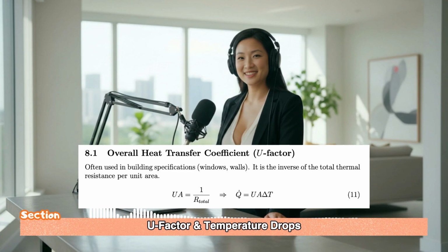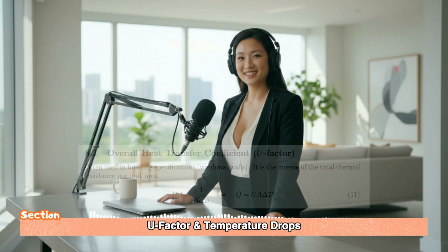UA must be the inverse of the total thermal resistance. UA equals 1 over R total. So if you look at it per unit area, U is just the inverse of the total thermal resistance for that area. This is the U factor you see on windows. Exactly. A low U factor means a very efficient, high-resistance system. And the reciprocal of the U factor is the R value, which is what you see stamped on insulation.